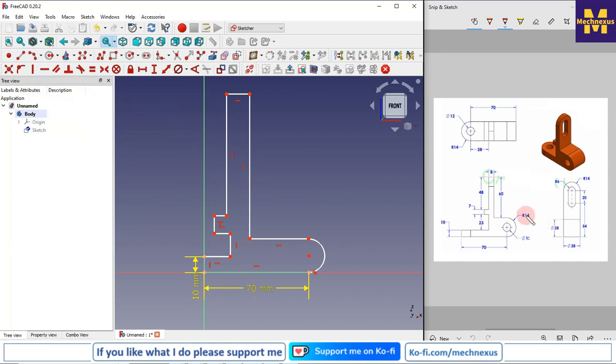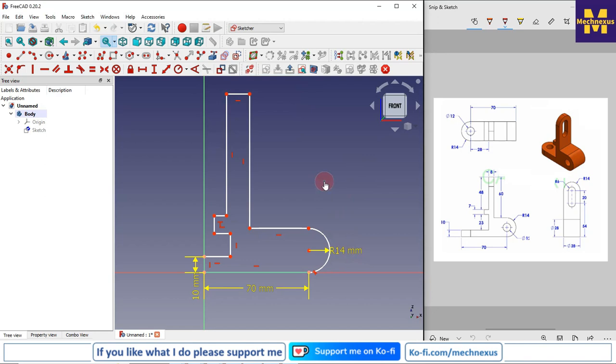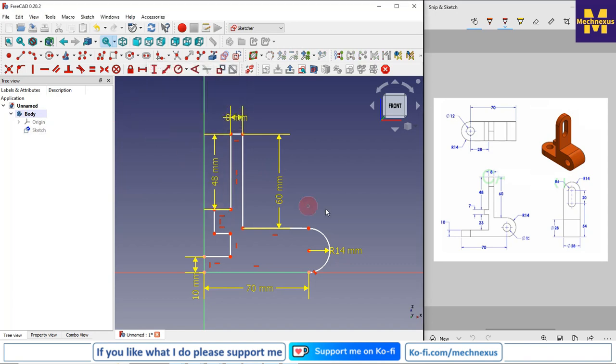Now this is the radius 14, so I will select this arc and give it a radius of 14. From this line to the top is 60, which we can see here, so I will select this line and give it 60. This is the 8, and this one is 48, so I will give the 48.